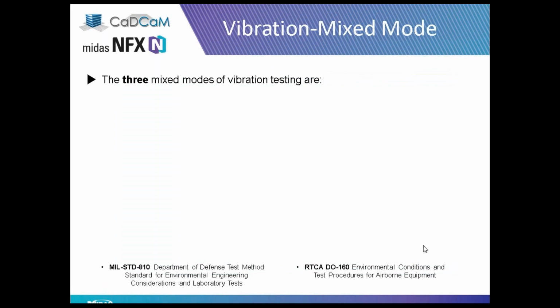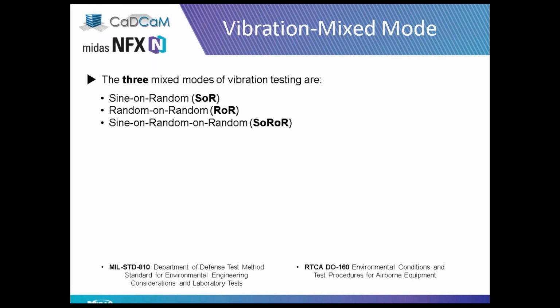So let's speak about the PSD curve type, which is called vibration mix mode. There are 3 mix mode vibration tests, and they are sine on random, SOR, random on random, ROR, and sine on random on random, SOROR.